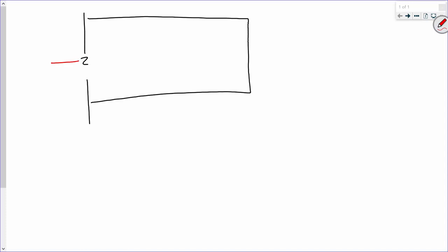All right. So let's say I'm loading this connection. Now let's make up some bolts. We'll do 1, 2, 3, 4, 5, 6. The first thing you need to do is identify a failure path that surrounds all of the bolts. Now I'm going to draw a failure path and then explain why that works. So let's take this one right here.